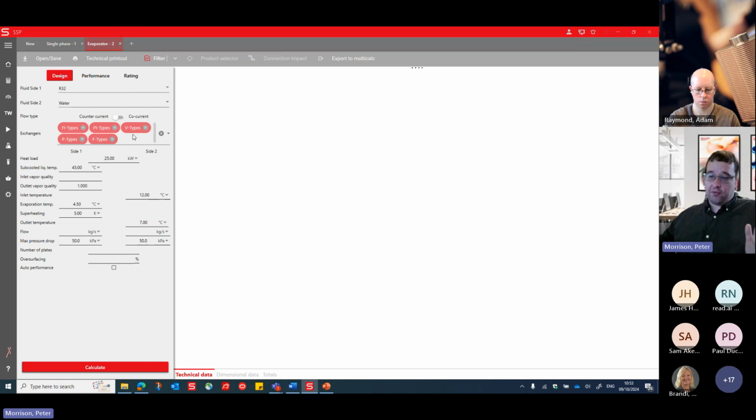With evaporators, if it's coming in as a liquid, it suddenly becomes gas, and the first thing is going to go straight up. It's not going to go through the full length, which is what you really need to get this thing working as you need it. So it'll start going up too soon, and then anything further back will be a lot less gas. That's what's referred to as maldistribution, which is something you want to avoid.